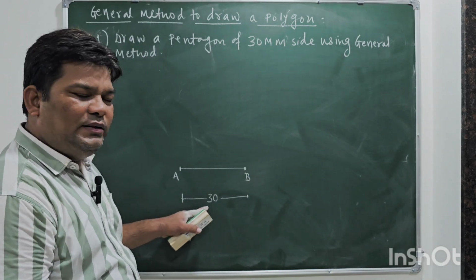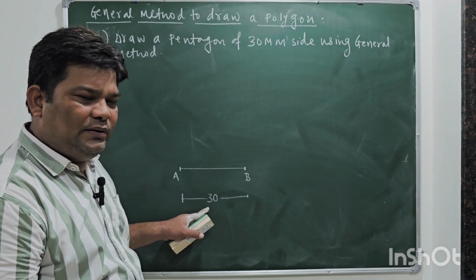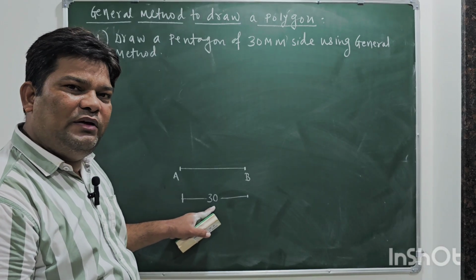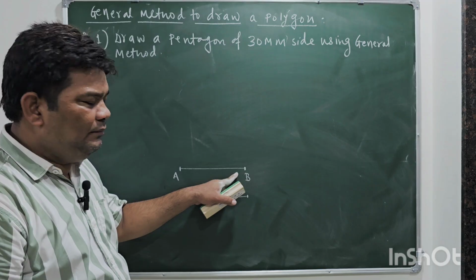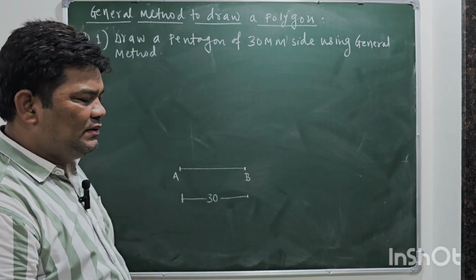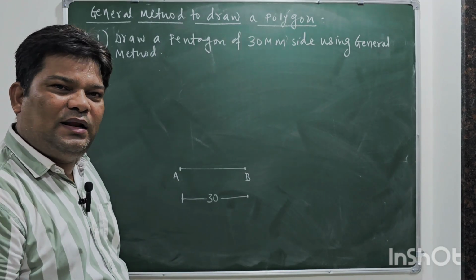You have to follow either the unidirectional method or the aligned method to show the dimensions. Any one method throughout. Now you have drawn a line of 30 mm, and given the dimensions. After that you have to bisect the line AB.